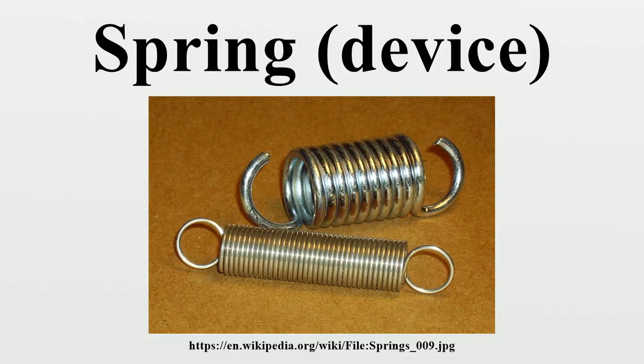Coil springs and other common springs typically obey Hooke's law. There are useful springs that don't. Springs based on beam bending can, for example, produce forces that vary non-linearly with displacement. If made with constant pitch, conical springs will have a variable rate. However, a conical spring can be made to have a constant rate by creating the spring with a variable pitch. A larger pitch in the larger diameter coils and a smaller pitch in the smaller diameter coils will force the spring to collapse or extend all the coils at the same rate when deformed.